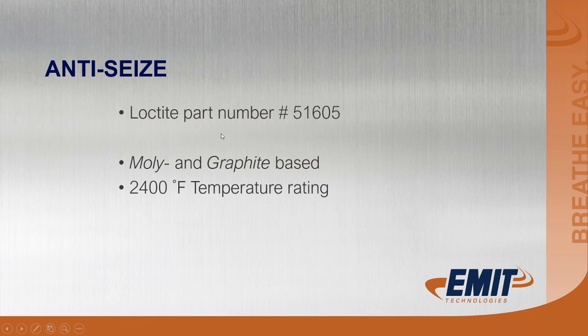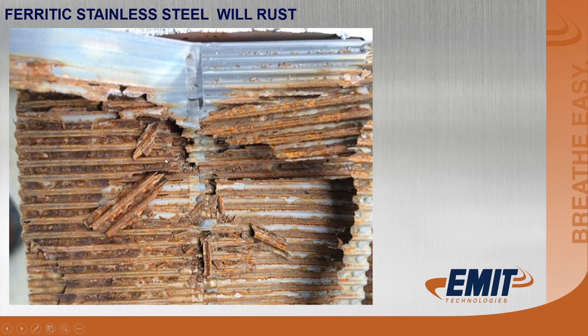Okay, anti-seize is another thing that poisons the catalyst. You always want to use a moly graphite based unit. H2S, it will definitely rust. Moisture, or water, is a normal product of combustion across the catalyst in a natural gas engine combustion process. And when you mix that with H2S, it's not a good thing. It would cause rusting very fast.